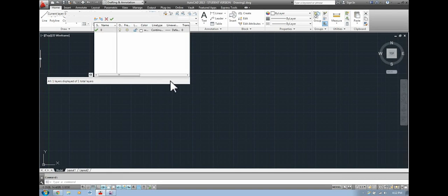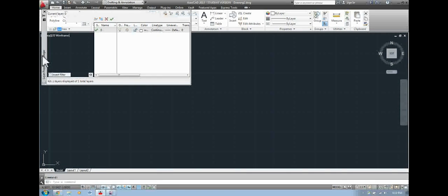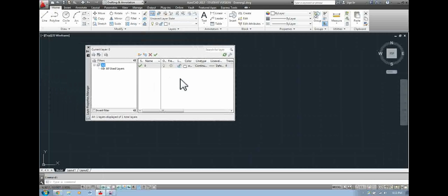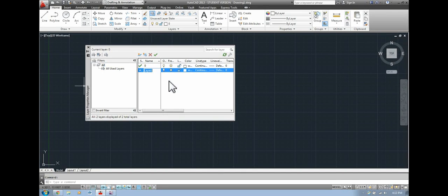And here I'm going to create some layers. Okay, here we go. Took it a while. To create a layer, either use the hotkey Alt-N or just click this new layer button. Since I'm not going to be seeing exactly the names of your layers, you can name them how you want. I'm going to name this one Rectangle. And then I'm going to create a new one and call it Object. And then I'm going to make a third layer called Center Lines.